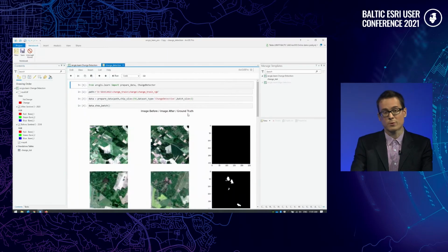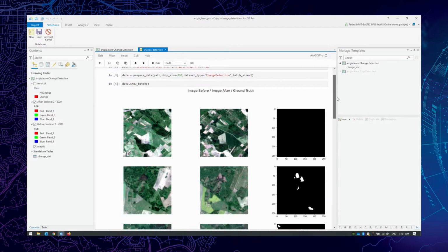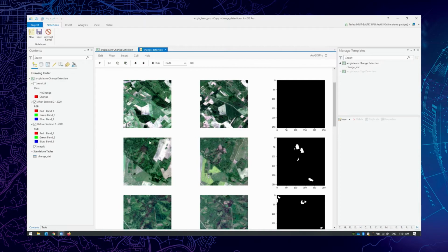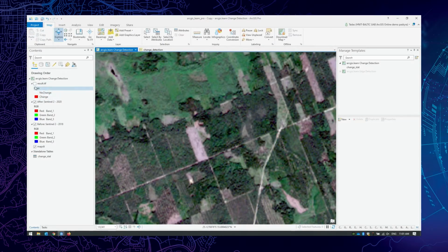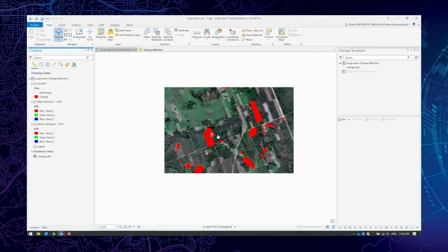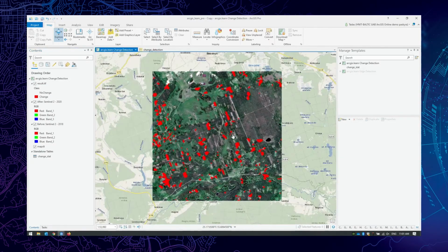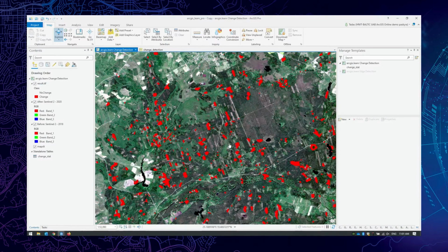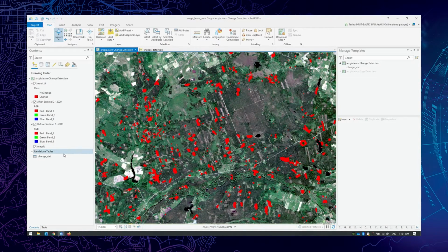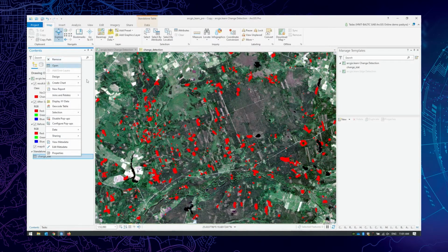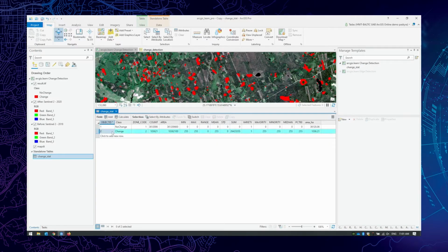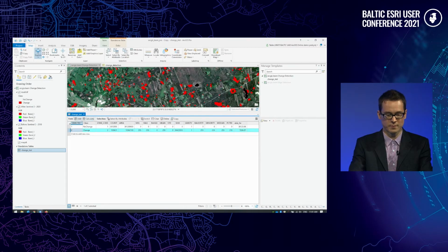It requires a few lines of Python code. It takes as input 3 images, so an image before change, an image after change, and then a raster mask which shows where the change has happened. When I run this tool in ArcGIS Pro, I get this result, which visually shows us the areas where there's possible forest cutting. I can also quantify this result, and I can tell you that, for example, in this region here, we had around 1,000 hectares of forest that has been cut.